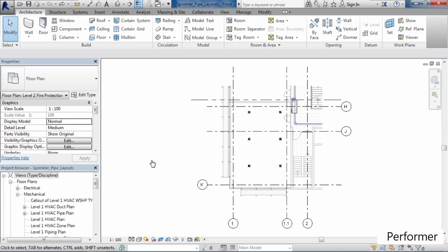Manual, basically drawing your pipes and routing your pipes from sprinkler head to sprinkler head, or to your mechanical equipment from the sprinkler heads. Or the second option is to allow Revit to lay out the pipes for you using the automatic method. Usually when you're laying out plumbing for sprinkler heads, it's pretty symmetrical. Straight lines, common path, common branches off of a main tree. So the automatic method is best suited for this type of design.